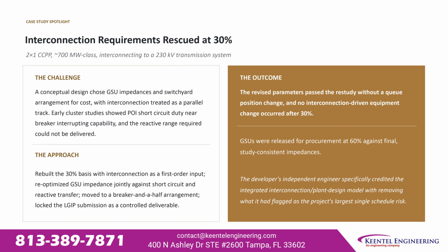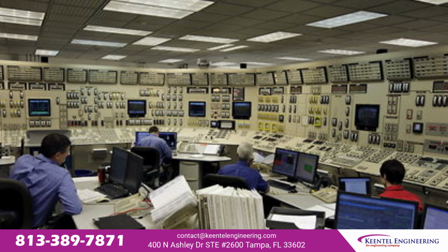The outcome: revised parameters passed the restudy without a queue position change. No interconnection-driven equipment change occurred after 30%. GSUs released for procurement at 60% against final study-consistent impedances. The project's independent engineer credited the integrated model with removing the largest single schedule risk.